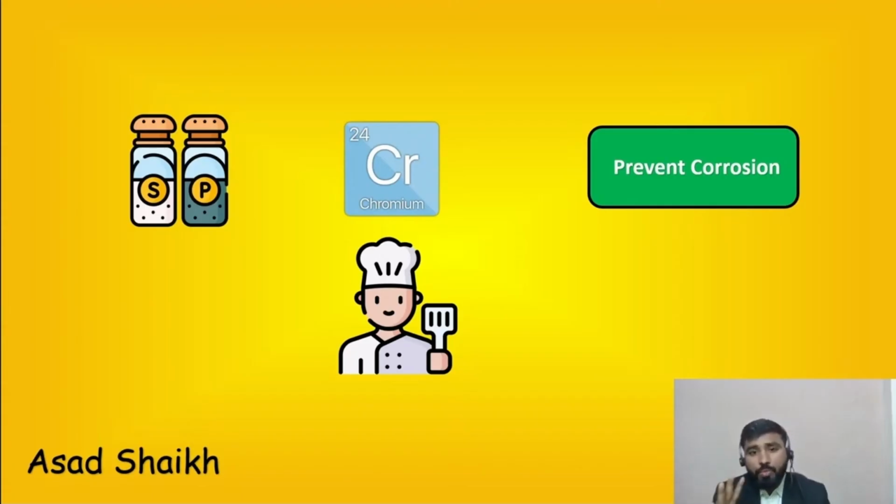So you should hopefully be good with the fluid. You are more corrosion resistant. However, be very cautious of the rating. It could be that your rating might be inferior and, for example, from a 300 flange rating, you might require it to be a 600 flange rating or 900 flange rating, depending on that. However, fluid wise, you are good to go.